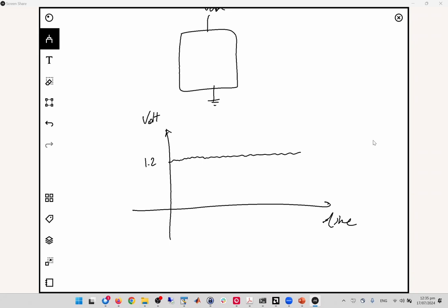With AC coupling, when you want to do a measurement in AC, you completely remove this DC shift. It comes down and will be around 0. Then you can increase the sensitivity and, let's say, zoom in on these fluctuations. Of course, this is in the electrical and analog domain.